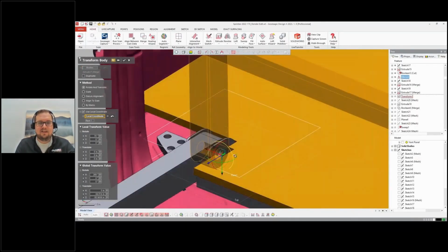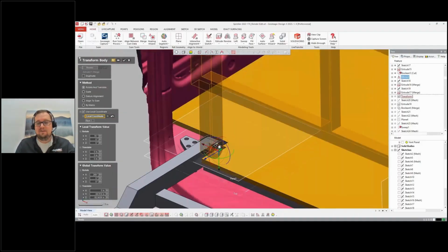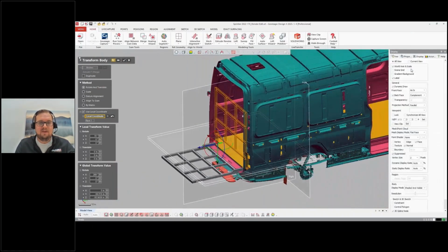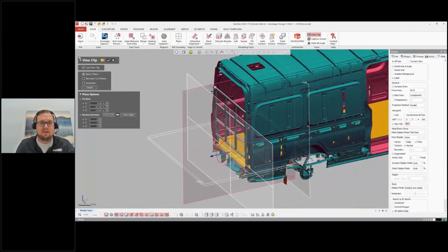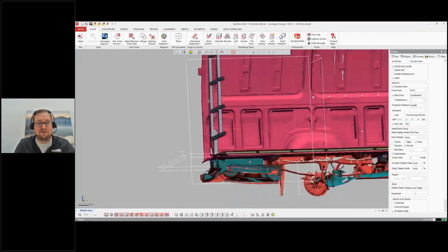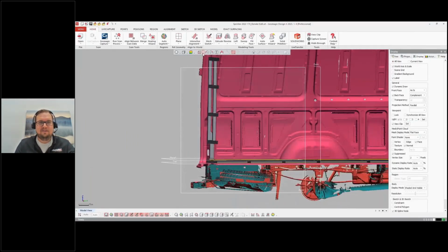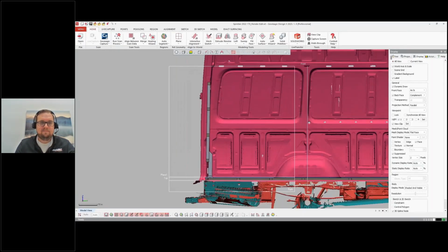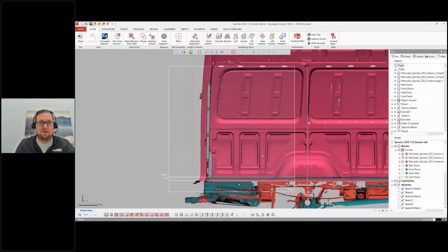Basically, I want to check, is it going to clear my door? Is it going to clear my floor pivots? How does the curvature of the rear of the van factor in? So I've just rotated my rear deck up on the actual pivot that I'm going to use. I can check here. I actually found that about 91 degrees gave me the exact clearance I need.